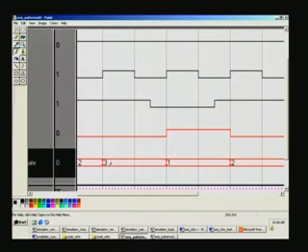So, the state changes at this point of time, but this output is dependent upon this state. So, it has just changed here, it has not yet stabilized, it gets stabilized only at this point of time. Because this is basically a state machine, it functions from clock to clock, not in between. So, what you have changed here, you have to wait for the next clock to arrive, then only the corresponding state will actually be processed.